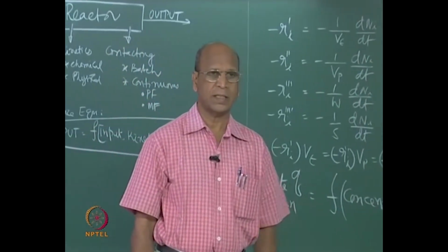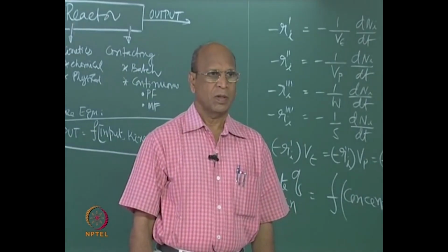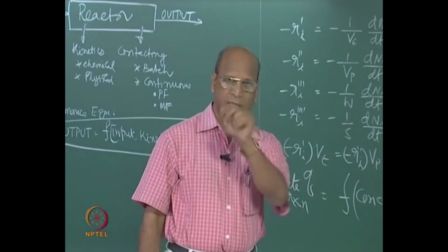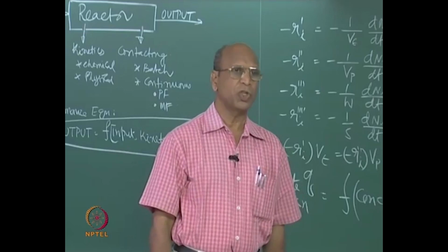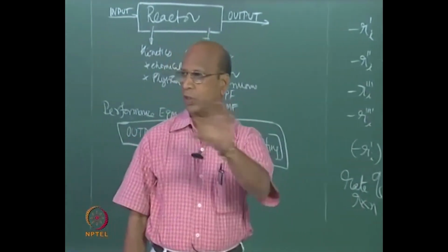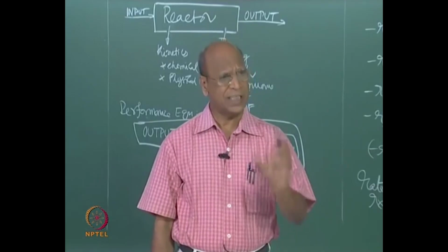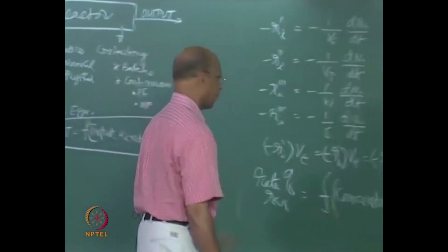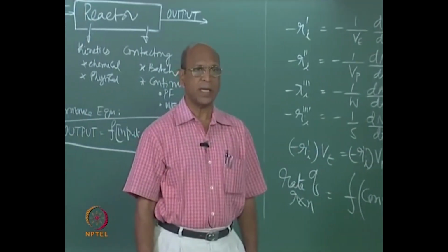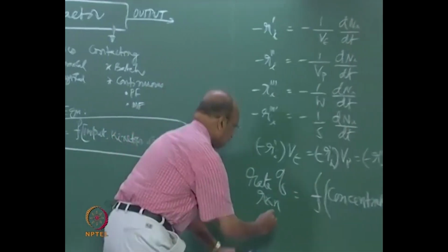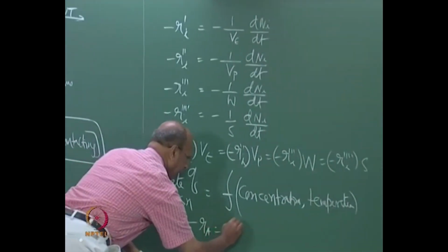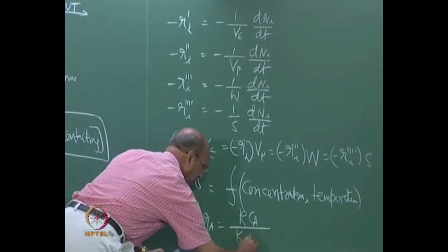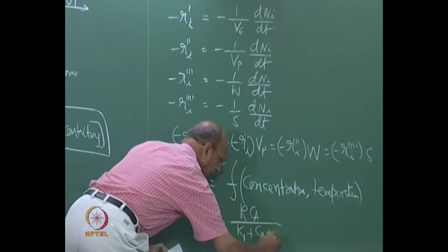What is the zero order reaction equation? Zero order means it is not a function of concentration; actually it is concentration raised to the power of 0, which becomes 1, so there is only k. That is the easiest, simplest one. Then first order, but from now onwards you should never think about the order of reaction at all. It can be any reaction rate, like in one particular instance it may be k into Ca divided by some constant, capital K1 Ca plus Ca square.